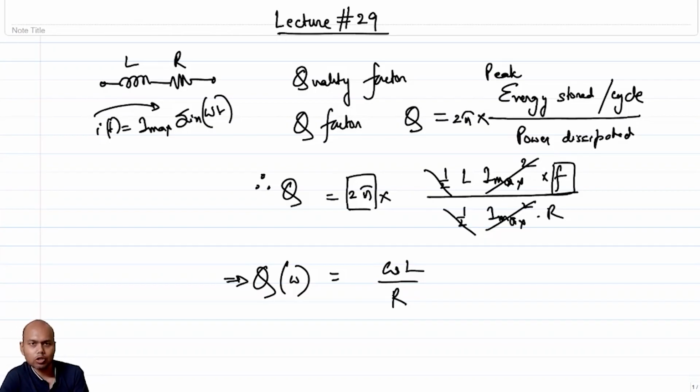And that is what we also saw without really defining a Q factor. If you recall, we saw some plots of imaginary part and real part and the loss, and when there is a self-resonant frequency, and before that we saw at what frequencies we'll have a peak value of the imaginary part, and then there will be a loss, and so on, right? All this is telling you is that once you get an inductor, you plot its Q and see where the Q factor peaks.